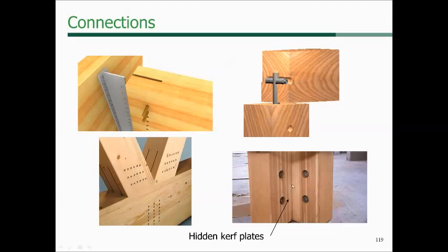This I don't believe is proprietary on this site, but it's a curved plate that's hidden up within the columns. You have bolts that are connected through, and then this would need some type of wood plug to cover the bolts of this member to prevent it from being exposed. These connections are actually proprietary connections, again, that are hidden within the wood member and covered with a wood plug to prevent exposure.